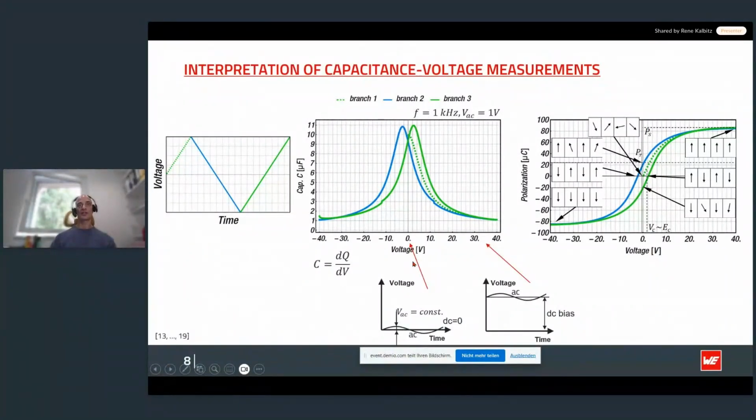During the measurement, a sinus probing waveform of a certain frequency is applied to measure the capacitance of the capacitor. The AC probing waveform has a fixed amplitude throughout the entire measurement and induces a small periodic change of voltage, delta V or dV. On the sinus signal, the DC voltage is superimposed then, allowing the reorientation of the domain polarization.